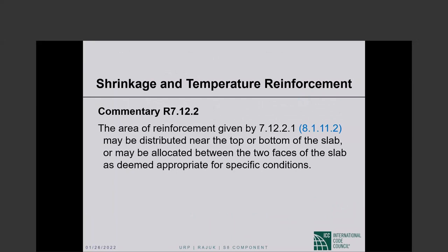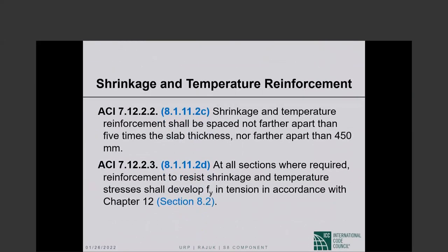So you will typically put it at the two faces. Maybe distributed near the top or bottom of the slab, or maybe allocated between the two faces of the slab as deemed appropriate. You will not put it in the middle.